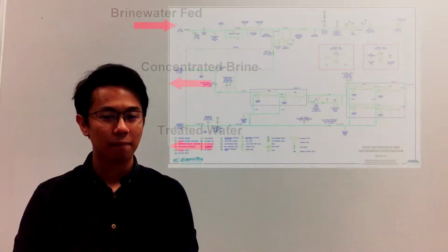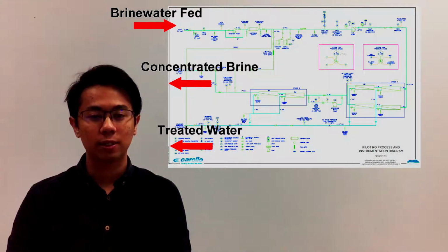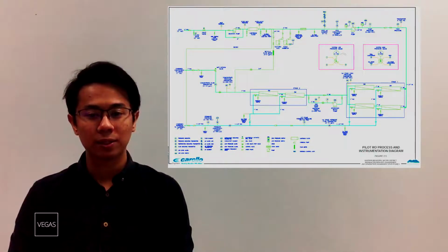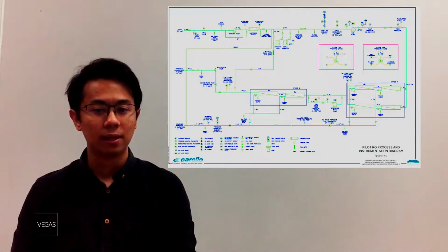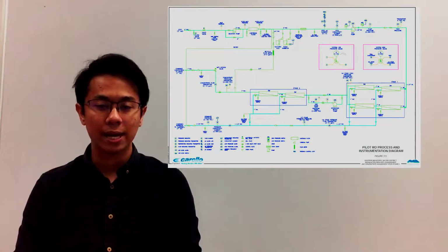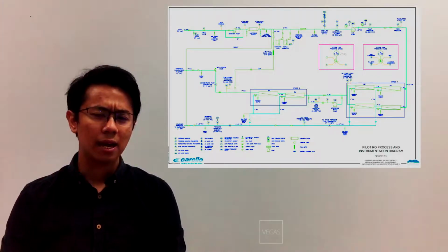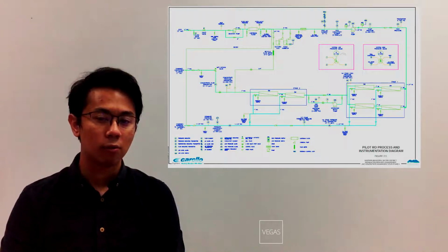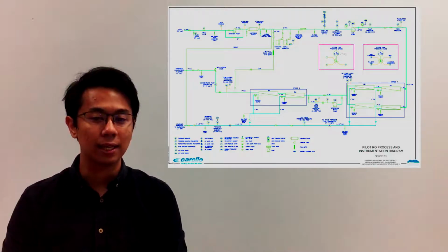Data analysis. Based on our findings, the reverse osmosis process can produce high quality water, given that the concentration of dissolved solids in the system must be less than 400 mg per liter, and the reverse osmosis membranes can perform at a recovery rate of 71% without any fouling. There are several improvements that can be made to achieve higher water purity. However, the silica concentrations must be consistently kept low.